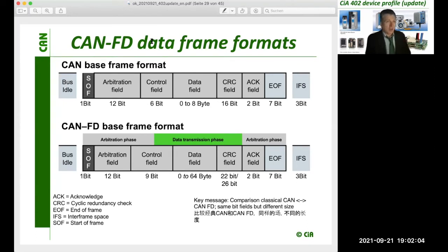The interesting thing is that now in the standard, CAN and CAN FD are together, so you have to look very closely at which one you would like to have, which controller. But if you do not develop the controller or transceiver itself, you don't need the specification. You just need to know what kind of controllers you need to purchase and what features they have to have based on the standard, for example.